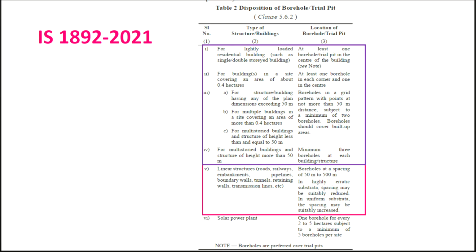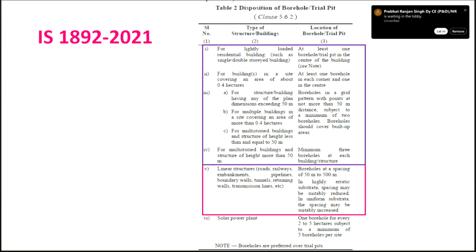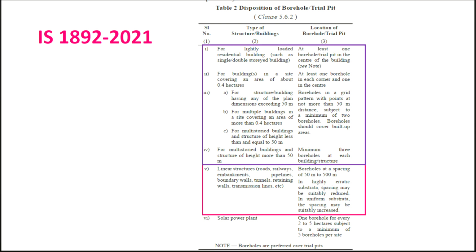The building is sinking even after 2 years in certain cases. So please mind well, subsoil investigations are required to be done very carefully, and more attention is required to the contractor who is doing all these activities. Please see whether he is taking the borehole samples properly or not, because based on those samples, laboratory tests will be done and certain inferences will be drawn.